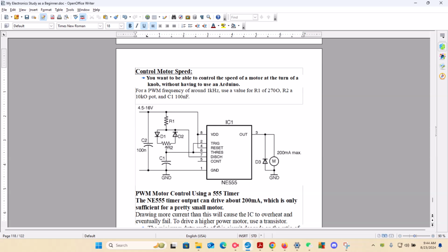It can also go to diode 2. The reason it'll go through diode 2 is because it's going in through pin 6 into the IC. Notice each one of these pins has a number and is attached to a function of the IC. Notice that the first pin of the IC goes all the way to ground. For pin 8, which is the last pin, that's going into the IC, which is the chip that's controlling the motor speed, and this will go out.